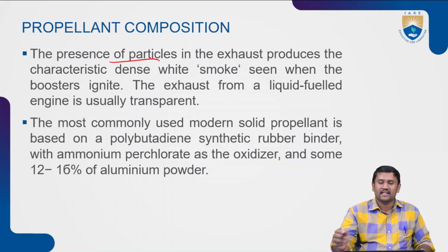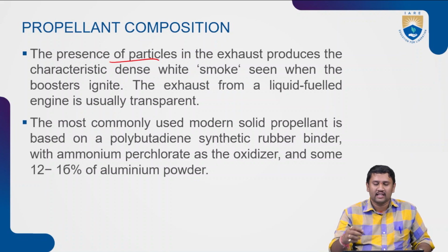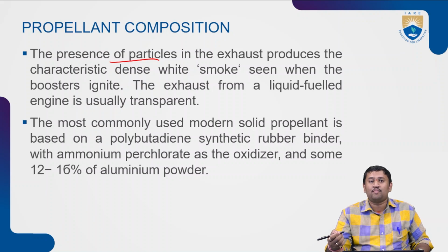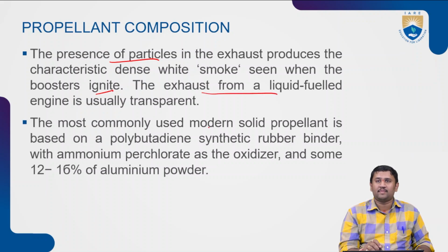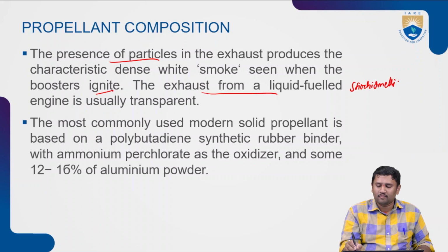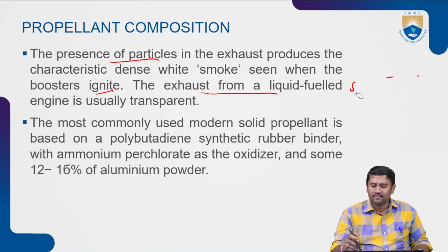The presence of particles in the exhaust produces the characteristic dense white smoke that we can see everywhere during a booster launch or a rocket launch. When the boosters ignite, the exhaust from the liquid fuel engine is usually transparent because that is burned under stoichiometric ratio. Right?